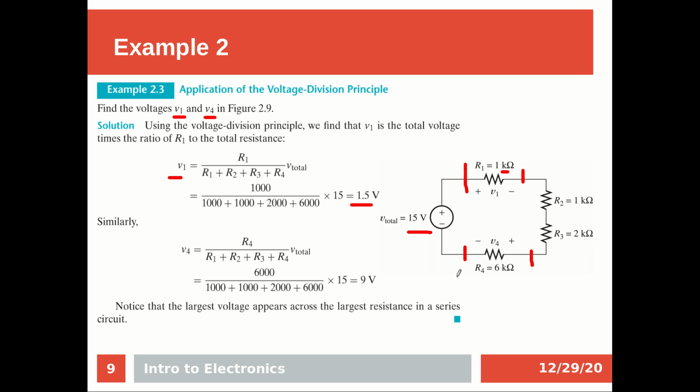You remember that all the voltages are V1, V2, V3, V4. If you take the summation of all of them, it should be equal to the V total. Remember that if you calculate all of them and find that the sum is higher or lower, then there is a problem. Okay, and take a hint for the polarities. You see the polarities.